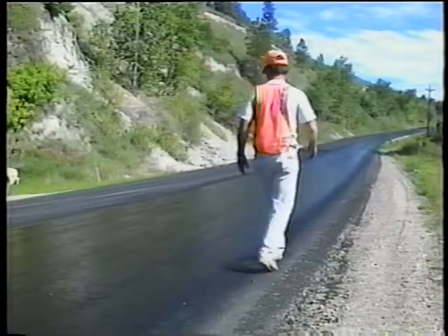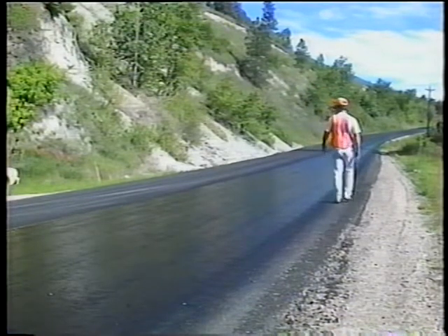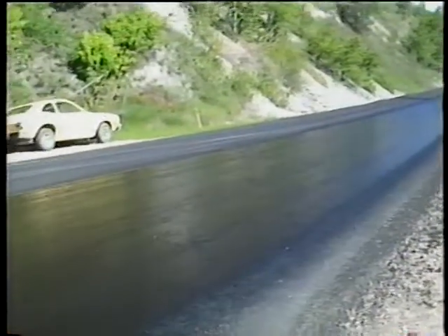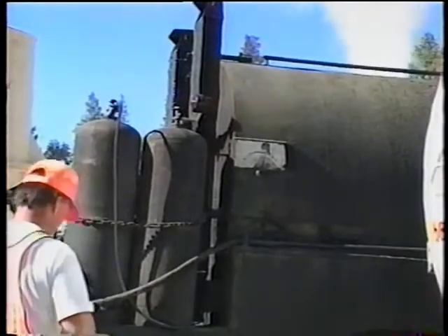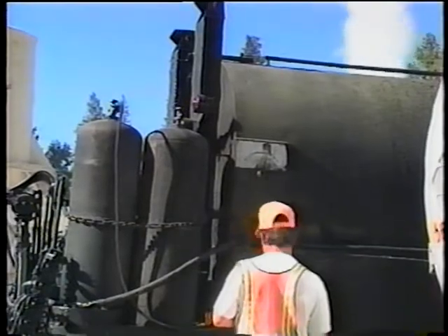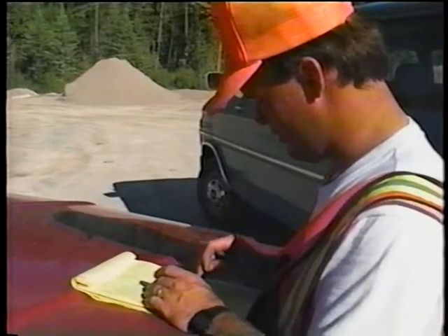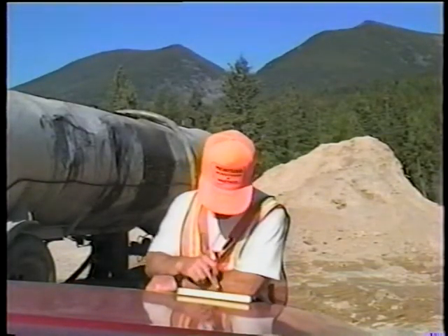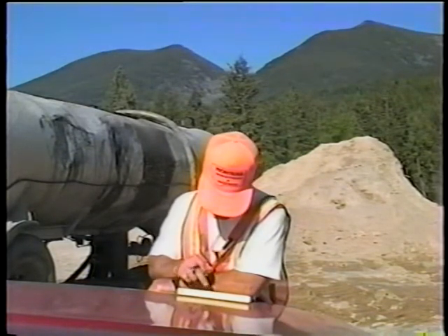Look over the application closely. If you see any bare spots or lightly covered areas, stop the distributor and get the problem corrected. It could be just one plugged or misaligned nozzle, so make the necessary adjustments. After the material has been applied, be sure to record the number of liters remaining so you can calculate the application rate. To do this, you divide the number of liters of tack applied by the area covered. The length of application times the width in meters. The rate is so many liters per square meter.